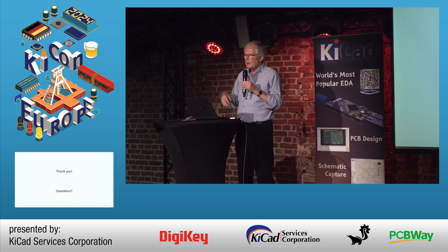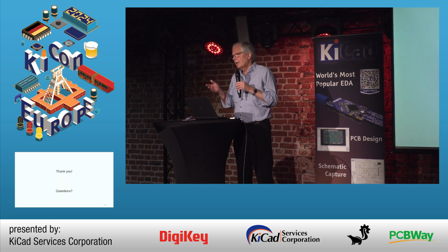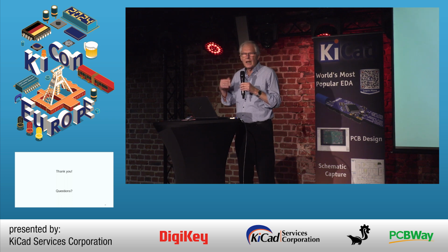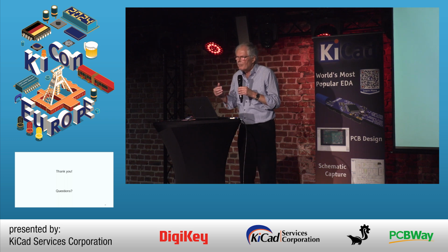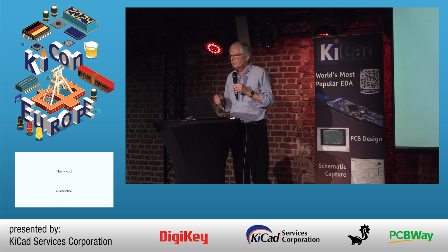So, same as you could say, okay, I need some additional devices to ease simulation, and I would not like to put them on the board. Or I have something on the board, connectors for example, which I would not like to simulate. Then you can exclude them from simulation. This can be done. Other people say, okay, it's better to make a copy.